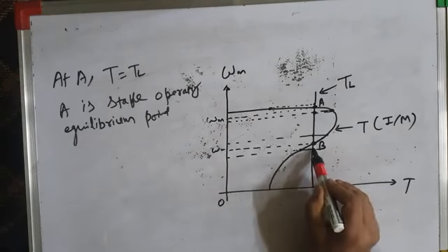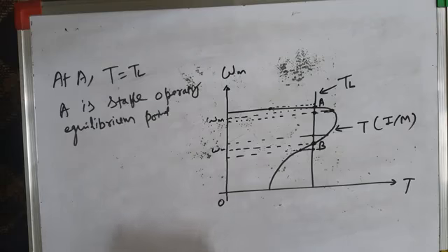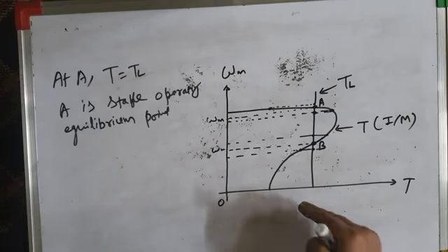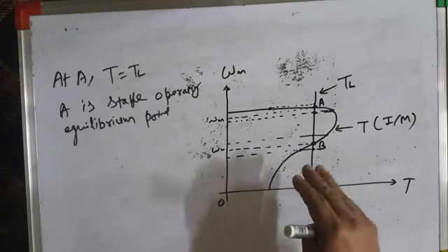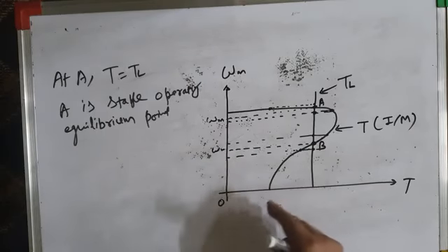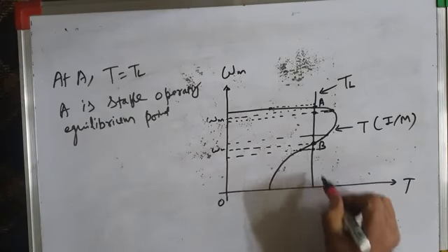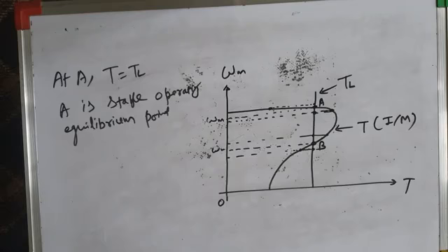Now you can see load torque is more than motor torque, and when load torque is greater than motor torque, it further causes slowing down of the drive. So the drive keeps on slowing down till maybe it comes to a standstill. So therefore it again runs away from its original operating point.